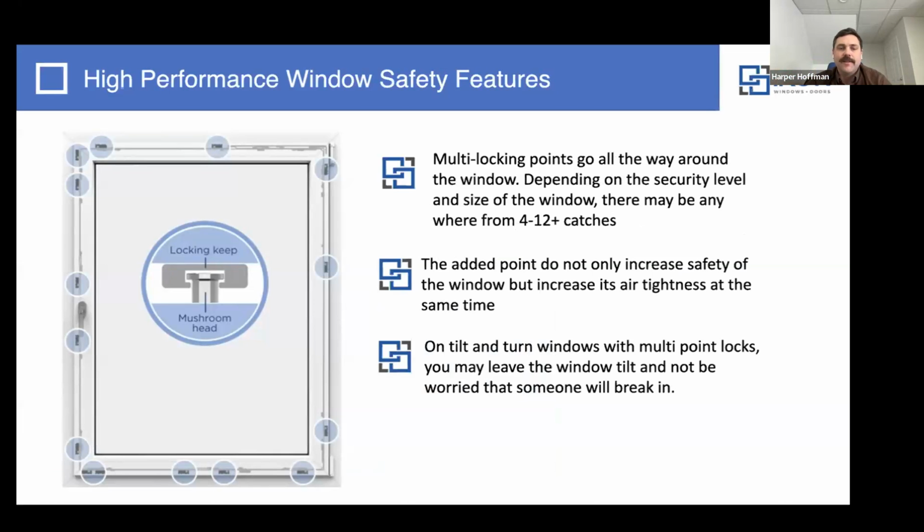So you're not going to get that with a double hung. You're not going to get that with a plain casement. You really want a tilt and swing with a multi-point lock system. And I can't stress this enough, how much of a difference this one single component can make with your window. And once you play around with these types of windows, you can instantly feel the difference and really comprehend what a difference it makes to the energy. You're not going to have air leakage at all.